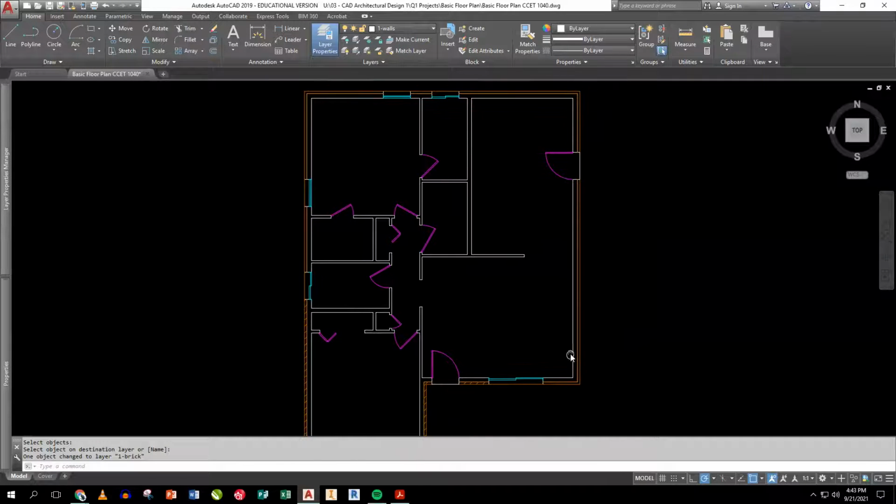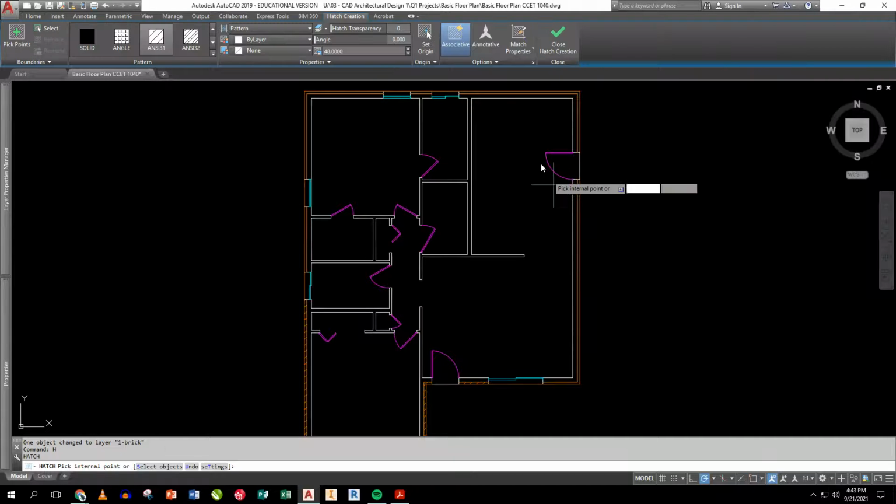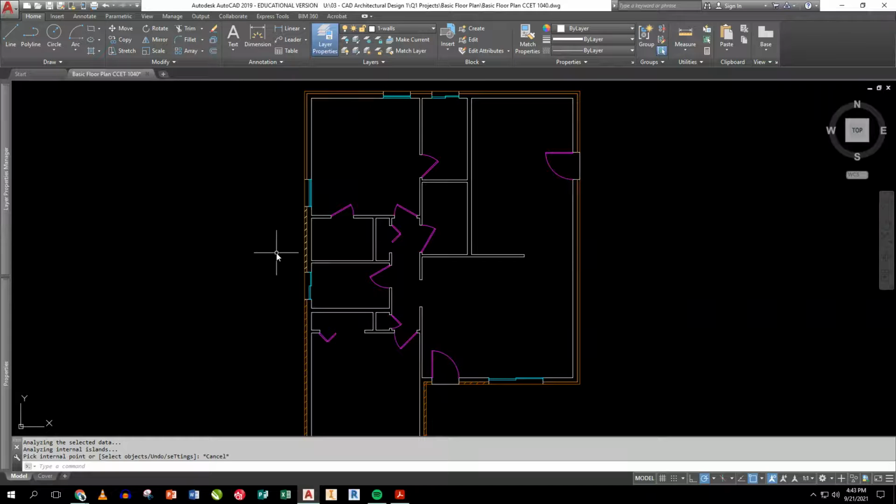Now, as I go around my building and do that, I have to make sure I fit that view inside my piece. It's kind of like a flood fill when you do it, so I have to get right in the right spot to put it in there, okay? So it gets really awkward at times, okay? Important things to do when you do this is make sure you're on the right layer. So make current layer, that one.